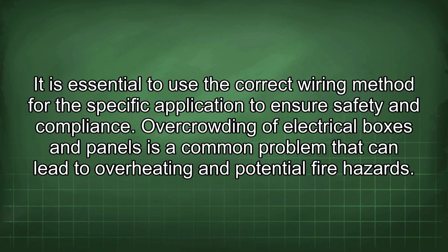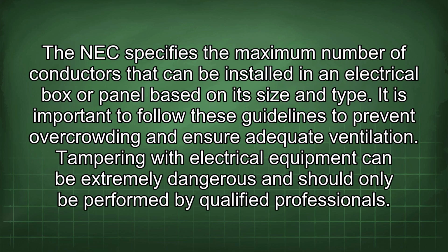Overcrowding of electrical boxes and panels is a common problem that can lead to overheating and potential fire hazards. The NEC specifies the maximum number of conductors that can be installed in an electrical box or panel based on its size and type. It is important to follow these guidelines to prevent overcrowding and ensure adequate ventilation.